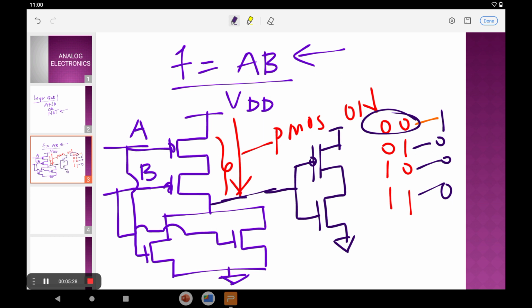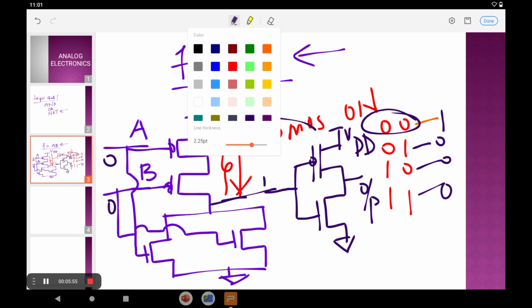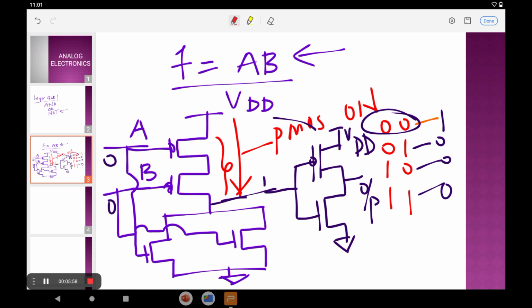This is also connected to VDD. Suppose you want to connect it from this to here, there is a connection also. So in case you are representing this, the output is also equal to the following. Suppose you are getting a 0 0 consideration, these are going to be a high output, therefore you will get a 1 value. So when that one is applied to the CMOS inverter, you will get a value of 0. Therefore, in this case, you will get an output of 0.